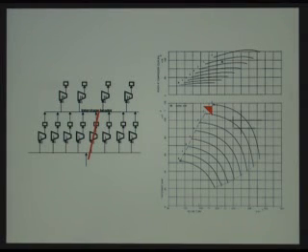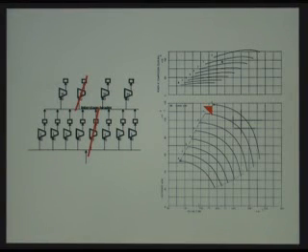The low pressure machines couldn't make up the difference, so these all ran out on their speed curve because the head rise went up until they finally hit their surge line, at which point that machine dropped offline.